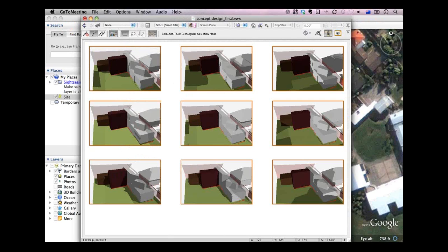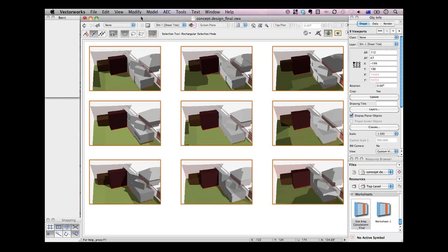Here we go. Can you bring 3D polygons in from Google Earth through SketchUp, then develop a site model for that in a variety of ways? If they're 3D contours, you can create a site model. If they're just 3D polygons, they don't automatically make a site model. They might make a site terrain, but a site model by definition is a particular special Vectorworks object which you can then use for creating contours, creating cut and fill.